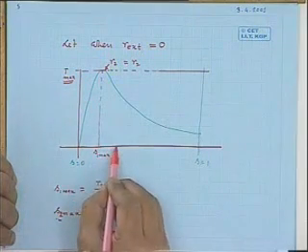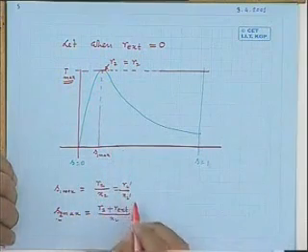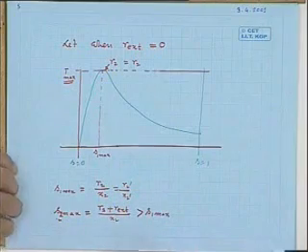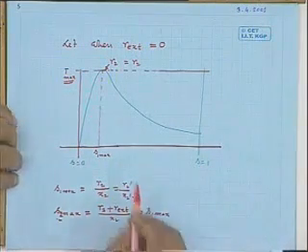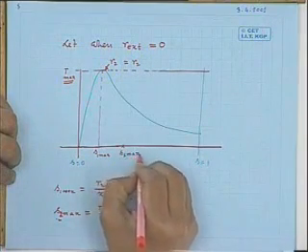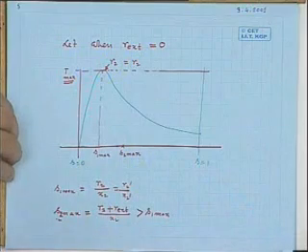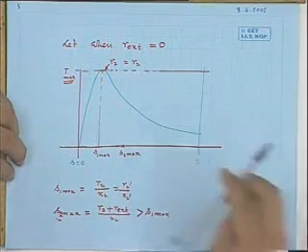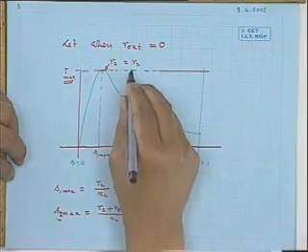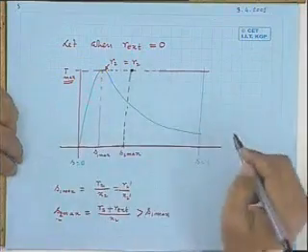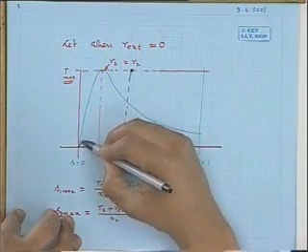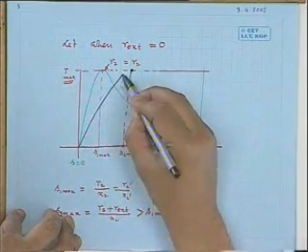Obviously, this slip will lie towards the right, greater than S1 max. Suppose this is the value of S2 max on the right of S1 max. If you draw a vertical line at this point, the T max point of the new torque slip characteristics has to lie there. Therefore, its shape will now be like this.